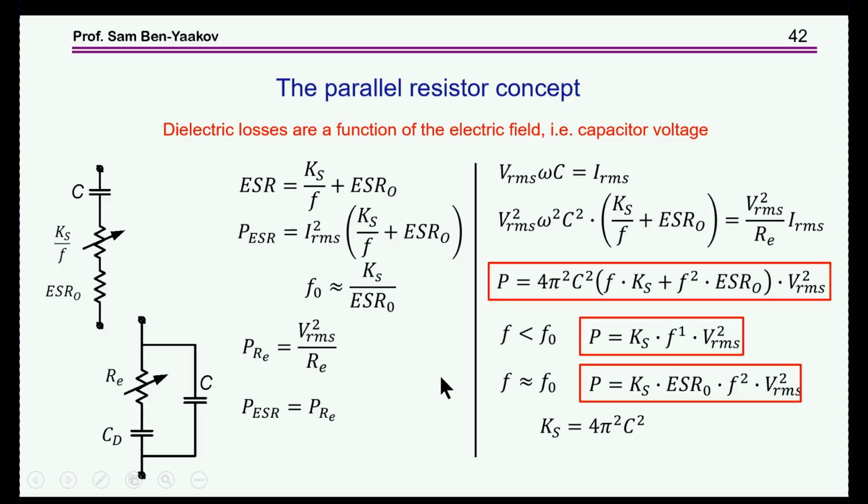Now, like in a ferromagnetic material, you can describe a loss either with a series element or a parallel element. In the case of a capacitor, if you put it in parallel, unlike in the case of an inductor, you can have DC. In an inductor, you don't have DC, so you don't have to worry about it.